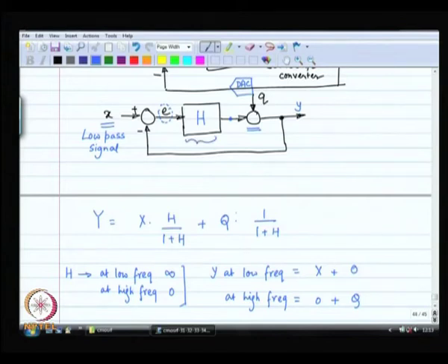This is some sort of an integrator, which means you are doing some sort of addition, sigma. And you have got a subtraction over here. So, that is the delta. Some people call it delta sigma because the subtraction happens before the integration. It really does not matter what it is called. The heart of it is a feedback control system. Now, you can build more and more intelligent transfer functions H to do better and better jobs.